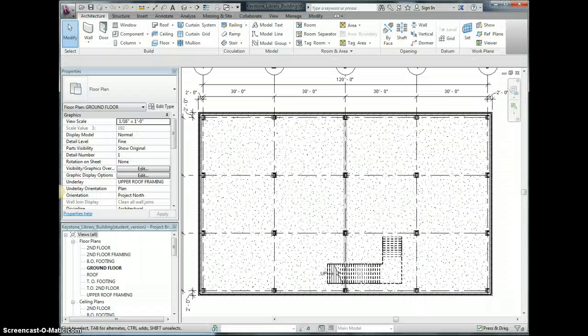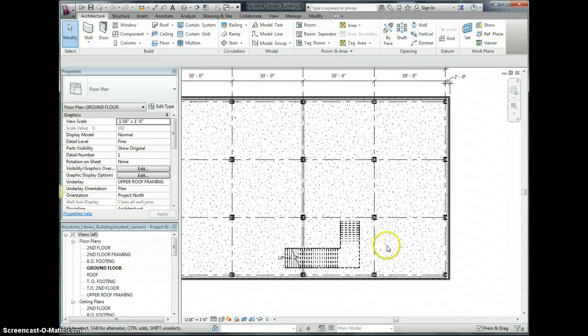I'm going to go back to my Revit file, and I'm going to put my elevator. This is all open space. You can see my opening, so I don't really want to put my elevator here because it would be in the open space. Obviously I can't put it here because that would open up to the green roof. So over here for me seems to make the most sense. Either that or I stick it somewhere in here. Maybe I'll put it here, oh no, I'll put it over here.